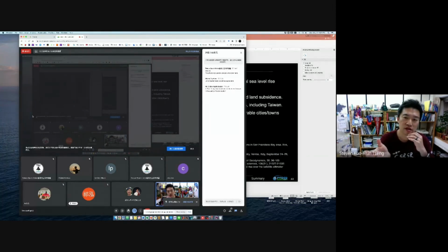So please follow this coherence rule. Don't ignore the coherence, and don't try to make a full coverage of everything using very low coherence. Otherwise, there will be a lot of noise and a lot of wrong patches that are very difficult to resolve. It becomes very, very disturbing.